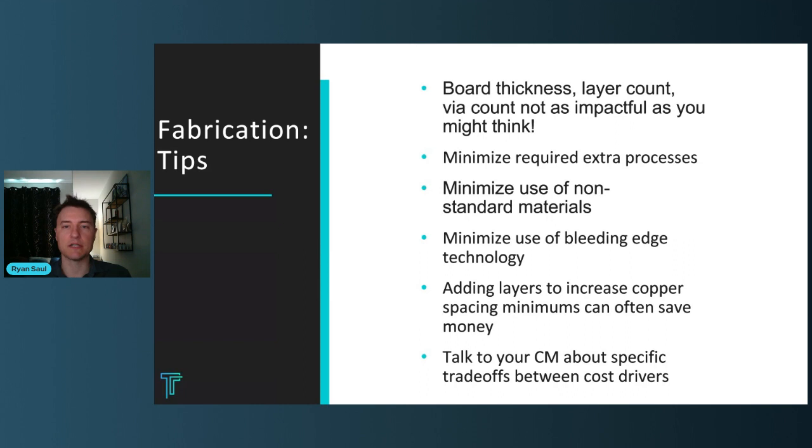defining controlled dielectric within your fab drawing is one of the biggest cost drivers that we see, because it necessitates zero flexibility on the fab side for dielectric type, dielectric thickness, and trace dimensions. That's not to say that it can't be done.